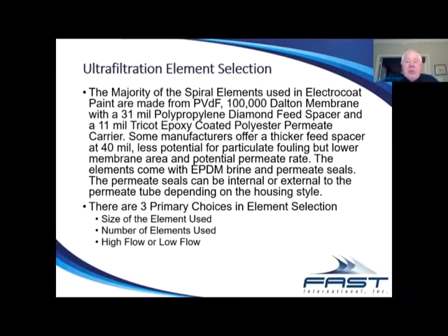In the element selection category, pretty much everybody in the industry is currently using a PVDF membrane that is 100,000 Dalton, and a Dalton is a measure of the molecular weight of the materials that it will reject. It's also referred to as nominal molecular weight cutoff.